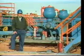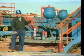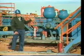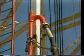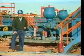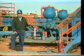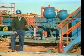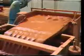While the driller is watching the Kelly and the weight indicator, the circulation system is doing its job. There we see the mud pumps displacing the mud from the pits up into the standpipe, through the rotary and swivel, and on down the drill pipe. When the mud has completed its journey to the bottom of the hole and exited through the nozzles in the bit, it returns up the annulus, carrying the rock cuttings with it, and exits the wellbore through the return line, leading to the shale shaker and on to the mud cleaning equipment.